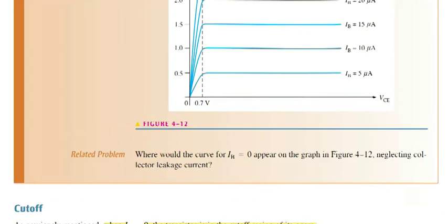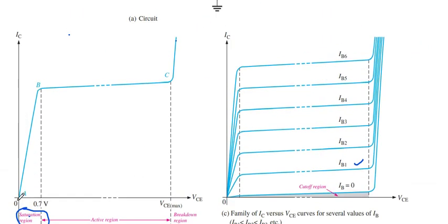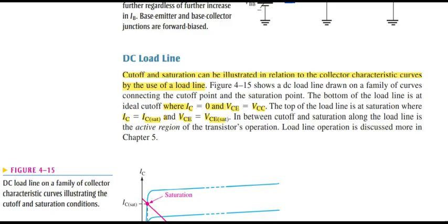I go back to the graph. There, if we increase IB, then IC also increases. At point B, IB increases while IC increases only very slightly as compared to the increase in IB. When it increases further, the breakdown region is reached. From point C, it goes into breakdown.